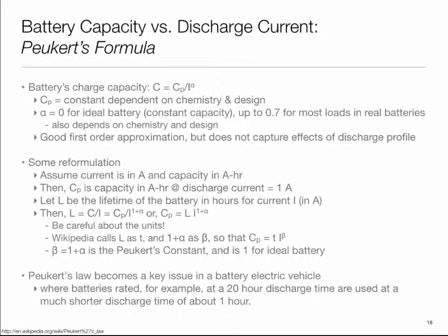In electric vehicles also, the voltages are much higher, so the battery packs are rated for 48 volts or something like that, so they have lots of cells in series. They use the same lithium ion cells that we use in our laptops, but a more gigantic pack made of them, and they use many of them in parallel so that they minimize the effect that we see because of this rate capacity effect.